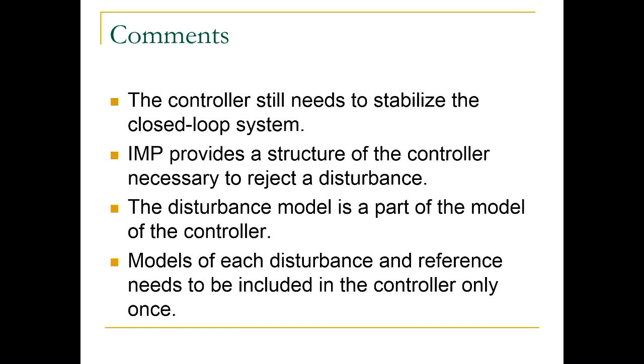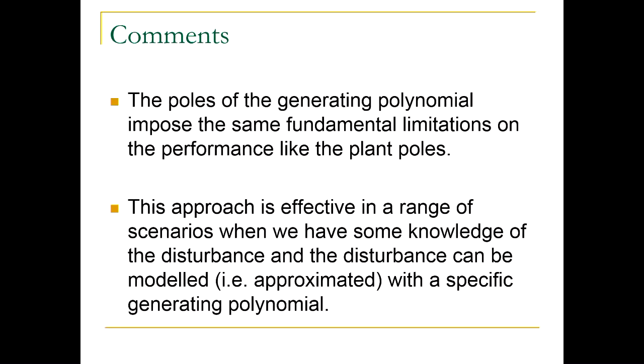You remember when we were doing integral control, we said references are step signals and disturbances are step signals, but we didn't have a double integrator in the controller. We don't need it. A single integrator would do the job, because a single integrator would model both disturbances and references.